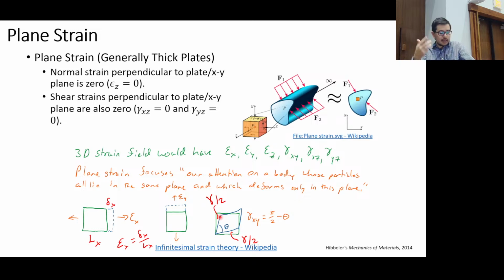So I always think that the shear strain is a little bit more confusing to describe, okay? But the sign is less important with shear strain, but it can be significant, right, in terms of thinking about is the material element in compression and tension. Because we've discussed this prior, some materials will have a higher yield strength in compression than in tension, the brittle materials in particular.